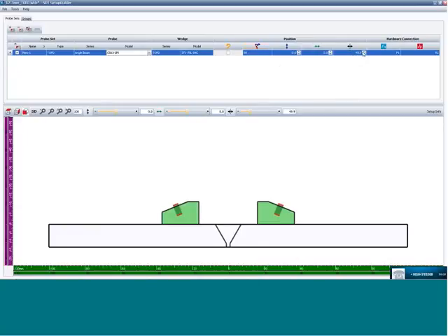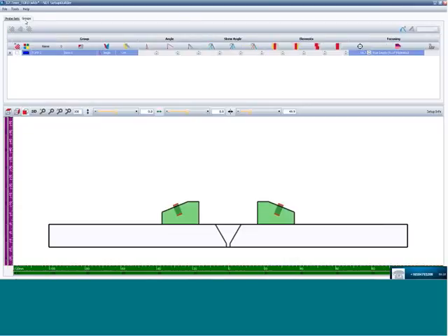The PCS is manipulated automatically based on the beam that we'll see shortly, and the pulser connection and receiver connection. For our groups, the TOFD group is automatically generated. We can select the color, and we chose to focus this at 66.7, or about 2/3 of the thickness of